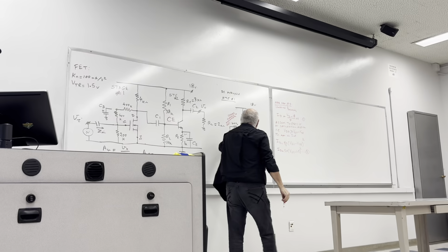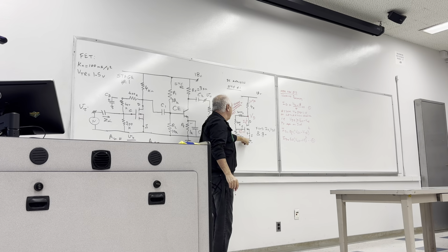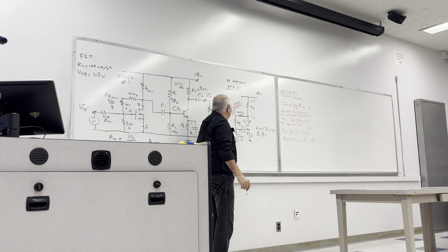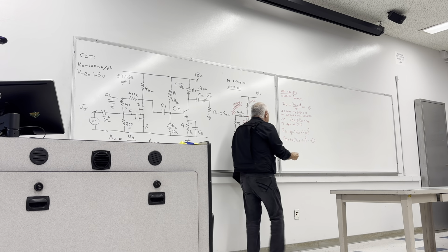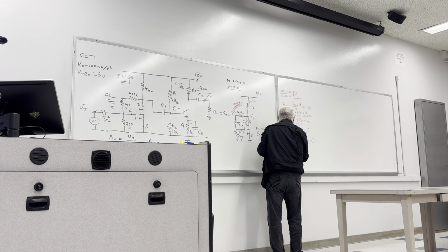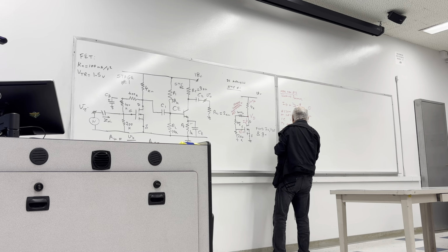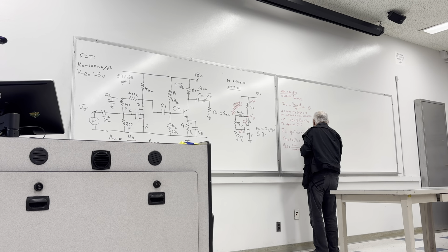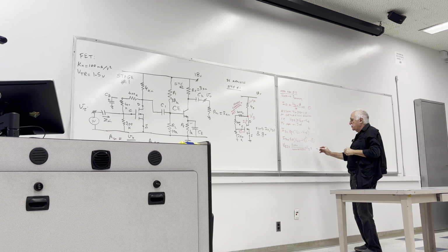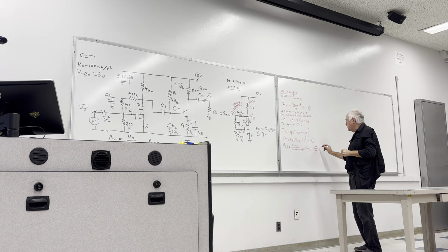What does that mean? If this node voltage with respect to ground is VD, then this makes a voltage divider. You can see 200, 400, 400. It divides that voltage. So we can say VGS is also equal to 200K divided by 400 plus 400, like series, plus 200, multiplying by V of the D. So that's equal to 200 over 1000. They're all K's.